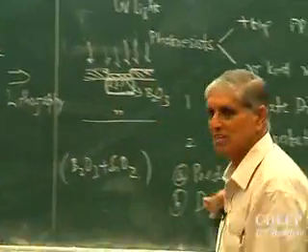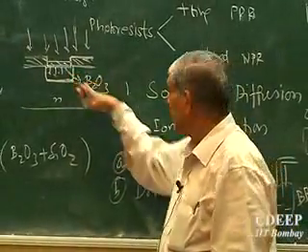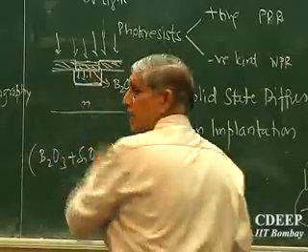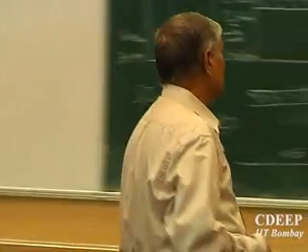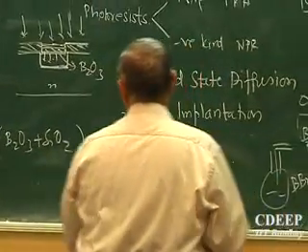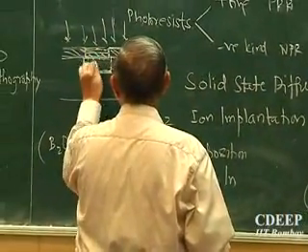So this is drive-in. By the drive-in process, the oxide anyway is now closing the P area. So what will happen? Since the oxide is closed on the top and boron has gone in, the impurity cannot come out, because otherwise they would be free to diffuse in either direction. So the glass actually protects the top, keeping the impurities in. They go down only in one direction and form a junction. So I now have a process in which I have created silicon dioxide even on the P area.